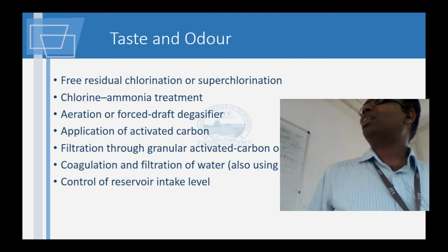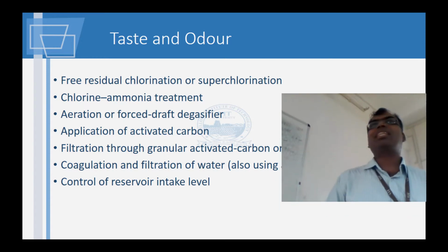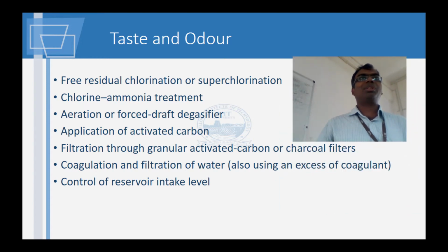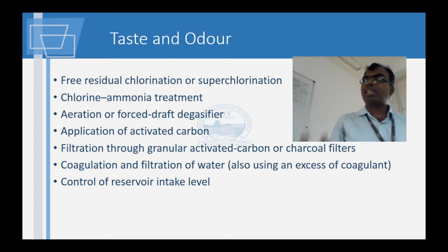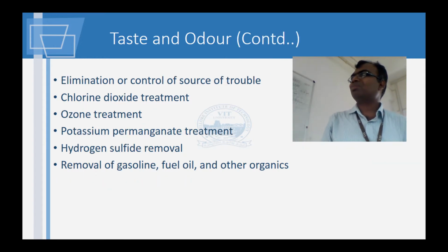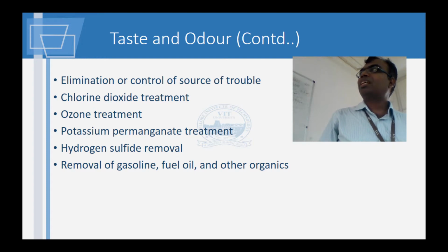Regulation of activated carbon. Okay. Control of reservoir intake. Yesterday we were talking, at different levels, you may find that there is more plant growth. Maybe at the bottom, these plants will also cause this taste and odor. These are microbes. So you might have to just take it at a reasonable level. If you go too deep, the temperature of water might even increase, or even the other way around is possible depending on so many other parameters, because sunlight doesn't go in. So anaerobic conditions could exist because of that also. So all these are just based on the localized conditions. Yeah, KMnO4.